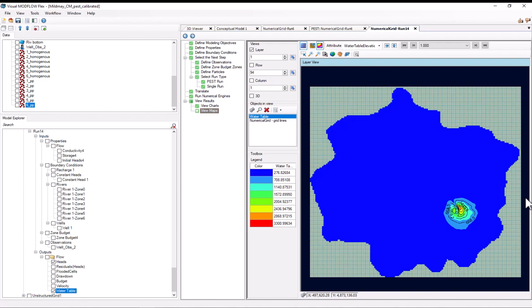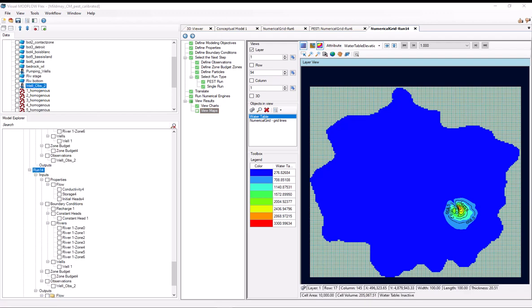So this might seem like something of a failed result, but this actually has an important takeaway for me as a modeler. I know that my conceptual model wasn't quite adequate. If I was running this as a real exercise, I might go back and change the conceptual model, for example, adding drains across layer 1, allowing excess water to be removed from the model, and perhaps then I could try another round of automatic calibration with PEST. Finally, I'll take a look at the calibrated parameters themselves.